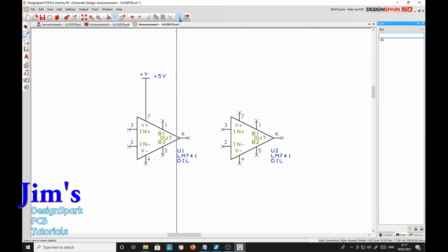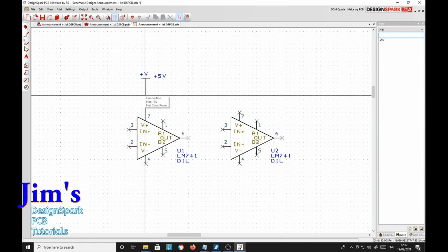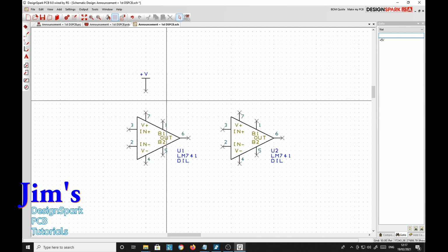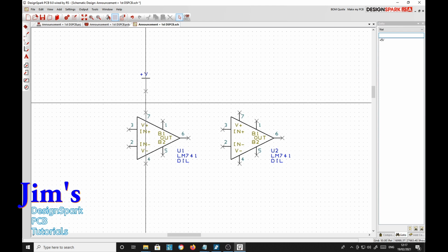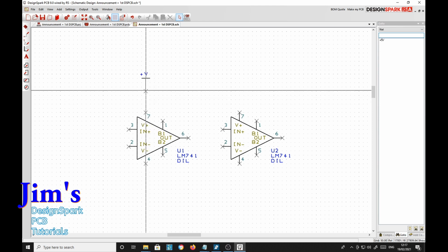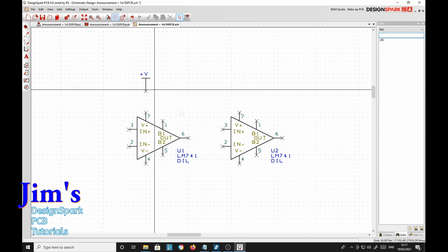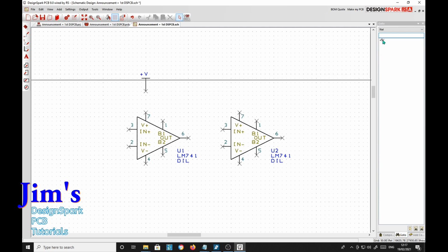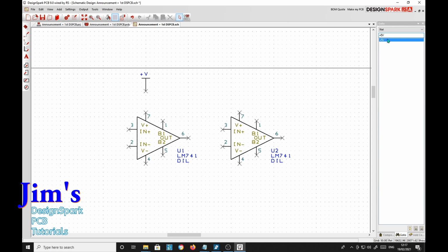Right, I'm going to go here to select mode and delete that, going backwards. Now there's another oddity. It's deleted the connection, it's put back the connection point, the reference, and it's also deleted the net +5. But would you believe it's left it up here? So if we click on it, nothing gets highlighted because there's no net, but it's left it up here.